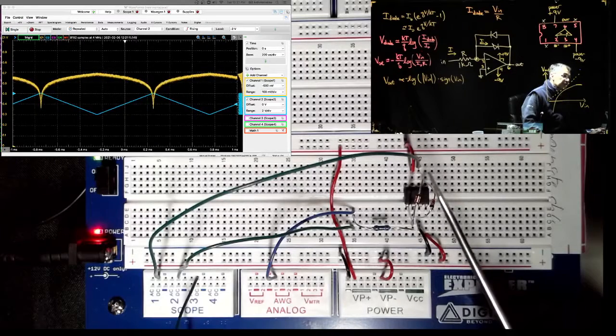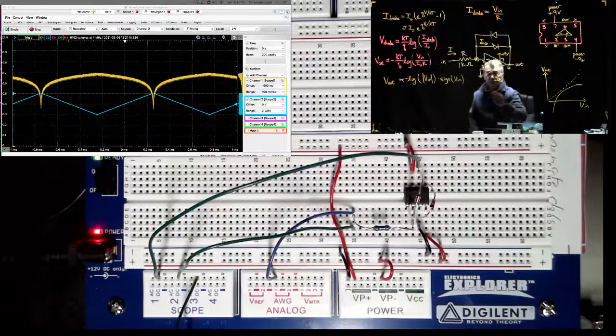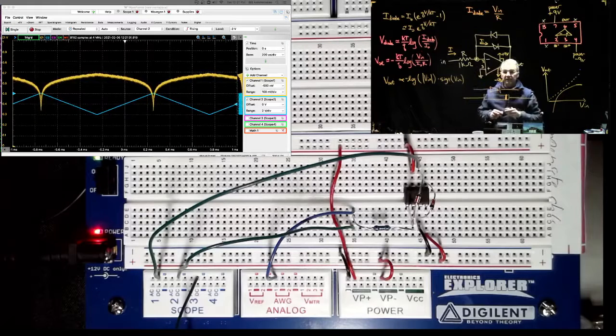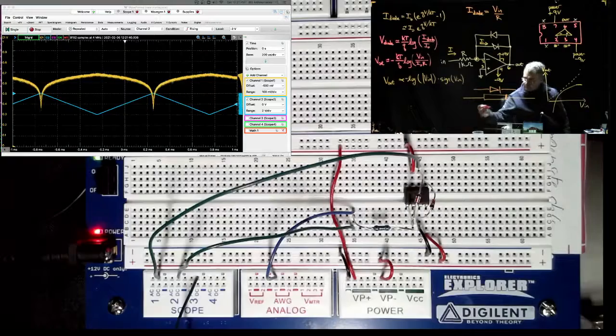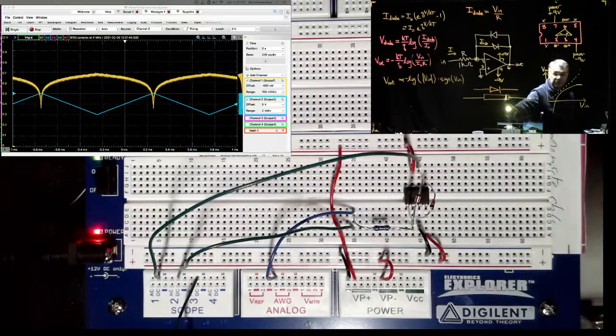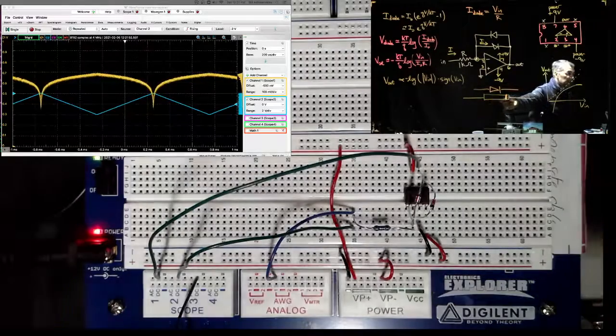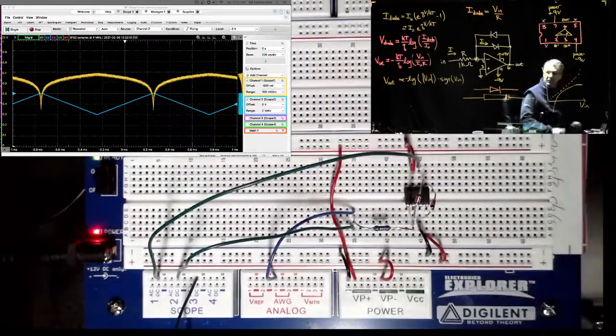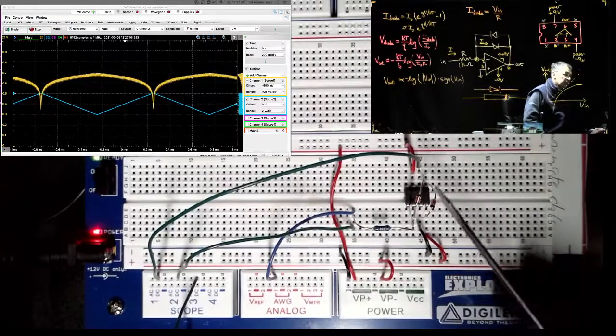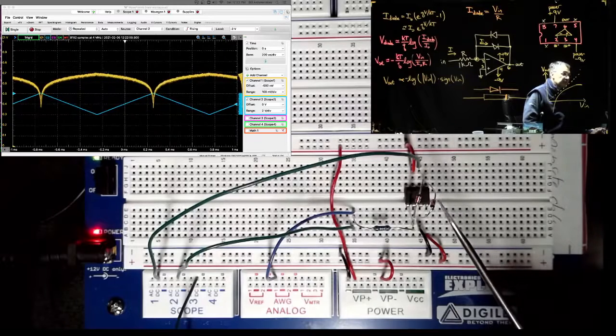And there's a little stripe on the diode package here. When you look at the diode, you see this long wire, and then there's a cylinder, and then there's another long wire, and there's always a stripe somewhere. That little stripe corresponds to the negative end of the diode when it's conducting. So the little stripe on the diode package corresponds to this line after the triangle. The direction of allowed current flow is toward the stripe, in the direction of the little arrow on the diode symbol. In that case, we had to connect one of them with the stripe pointing toward pin 2 and one of them with the stripe pointing back toward pin 6. So you have to make sure you put the two in opposite directions.